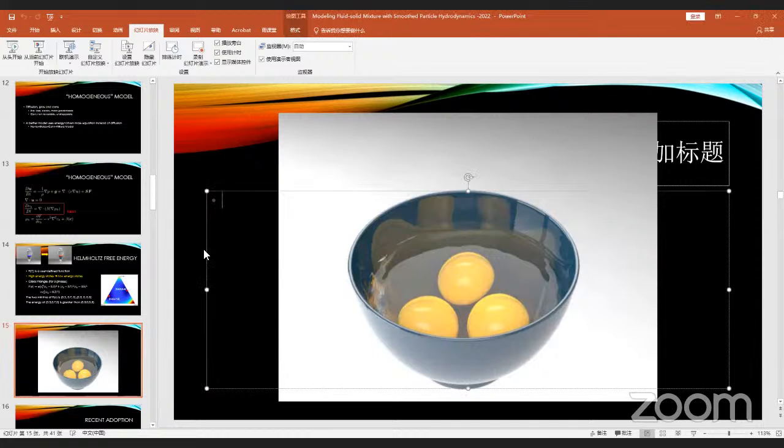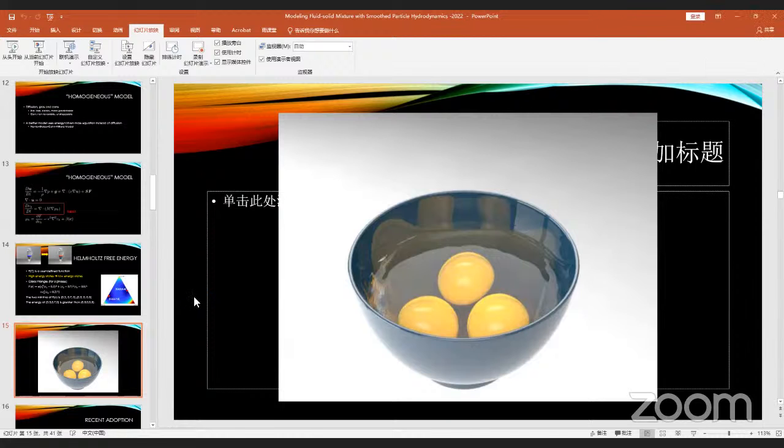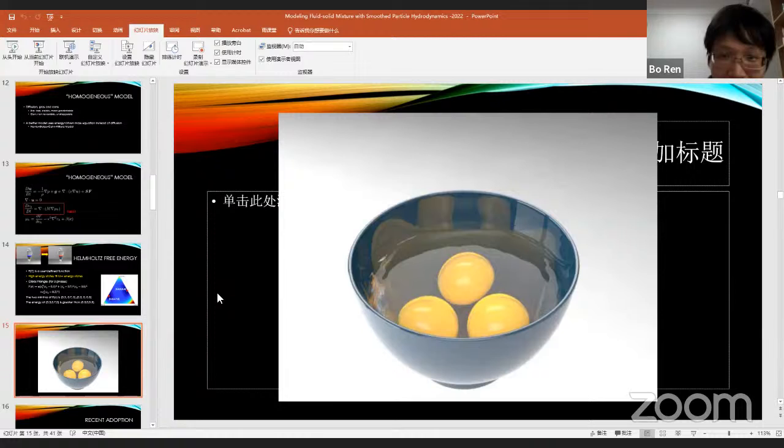For example, if you consider more turbulent flows, whether this kind of lower-order model can benefit stability and accuracy. Maybe this is a case. But another issue is that if you're using SPH, single-phase SPH turbulence is not very well resolved yet, so for multiple phases it's more complex. I think it's very interesting, and it deserves future research.